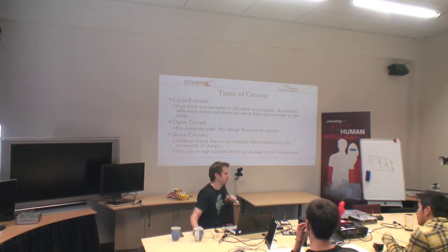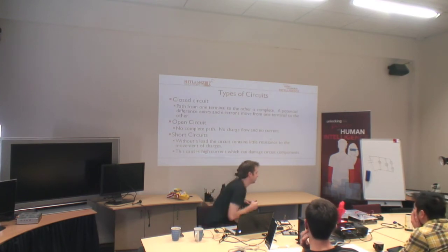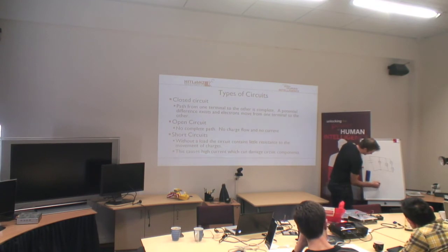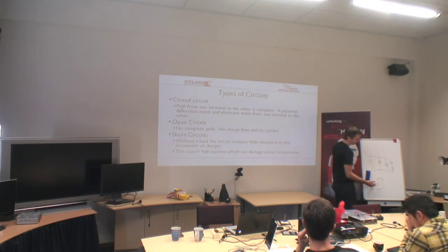Probably, unlike me, you should unplug your Arduinos when you're wiring them up and then plug them back in when you're finished. The bad thing about short circuits is basically, if you have something like this, you have your battery, and then it's connected with no load on it, it makes it incredibly easy for the electrons to get to here, so an absolute ton of them will move through, and this wire will heat up very, very quickly.